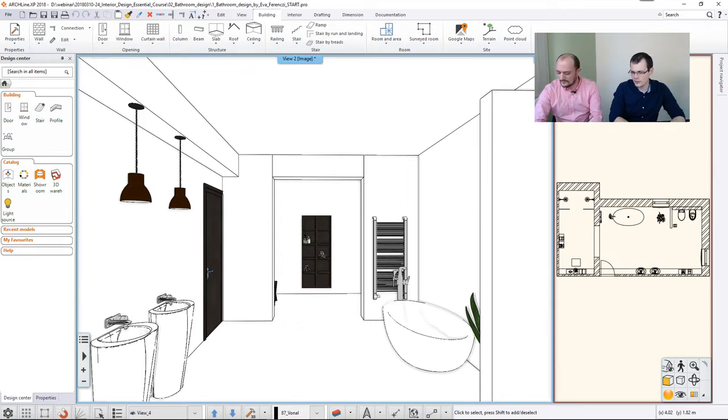That's right. One thing to clear up right off the bat is that when it comes to decorating your walls or any kind of surfaces with tiling, you could always use one piece of texture for that, but if you use the tiling methods that we are going to show now, you'll achieve two goals. One, the tiles will be part of your quantity takeoff, so you have exact estimations, and two, you have better control over the layout and how the tiles are spread.